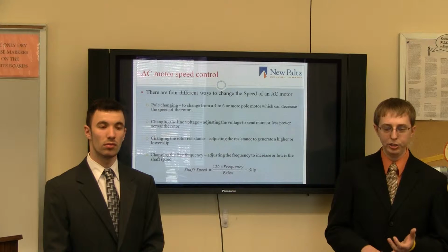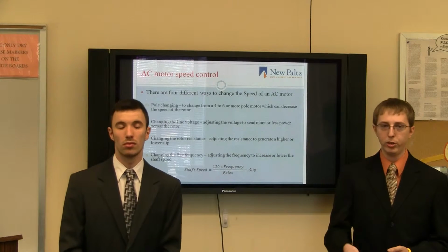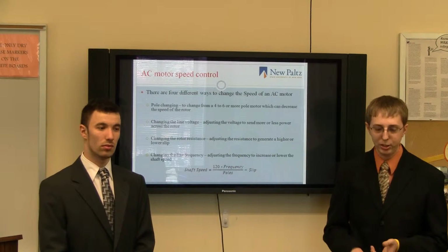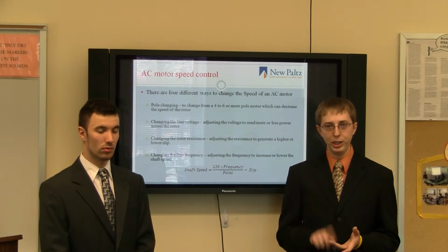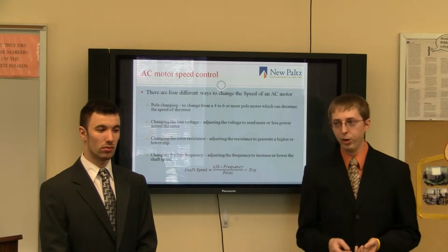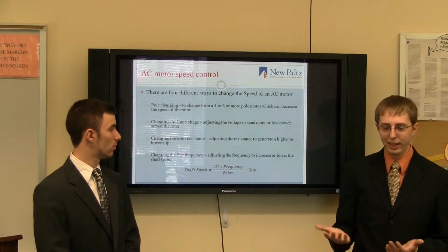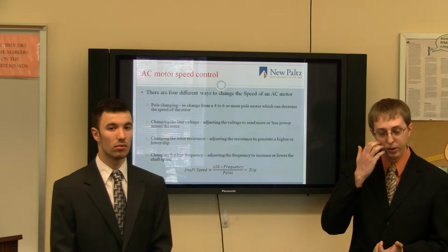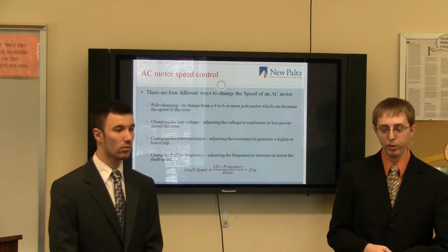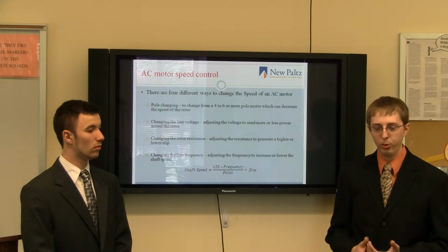Another way, you can change the line voltage, but when you change the line voltage, then you're creating too much power loss on your motor, so that's not good either. Same thing with changing the rotor resistance. If you change the rotor resistance, then that'll slow down your speed. So that's kind of costly too, because you lose your power through that. And so we want to go ahead with changing the frequency of the motor. By changing the frequency, there's virtually no loss of power through the motor.